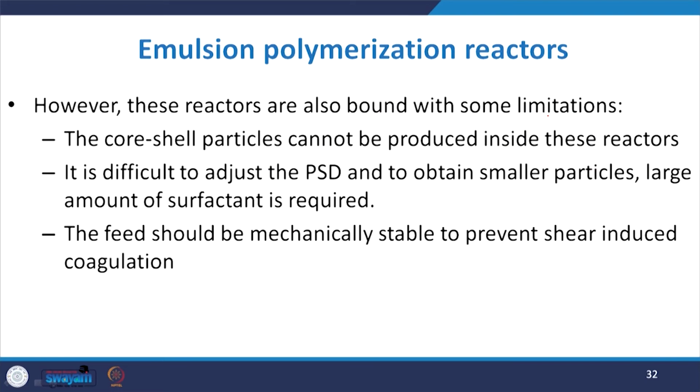Now, these reactors are bound with several limitations. Although they offer very good flexibility, they have certain limitations. Core shell particles cannot be produced inside these reactors, and it is difficult to adjust the particle size distribution and obtain smaller particles. A large amount of surfactant is usually required, and the separation of those surfactants from the produced polymer mass is sometimes a very tedious job.